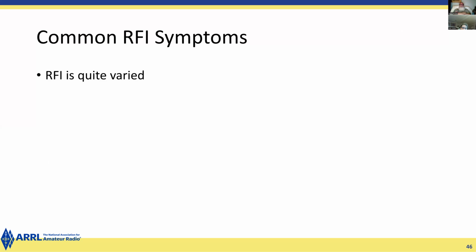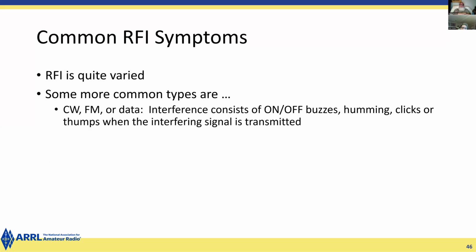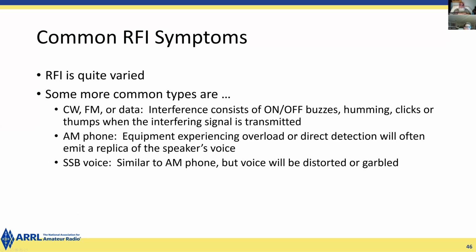So some symptoms are you hear on and off buzzes, humming, clicks, or thumps from things that aren't radios when you're transmitting, or when the interference source is transmitting.